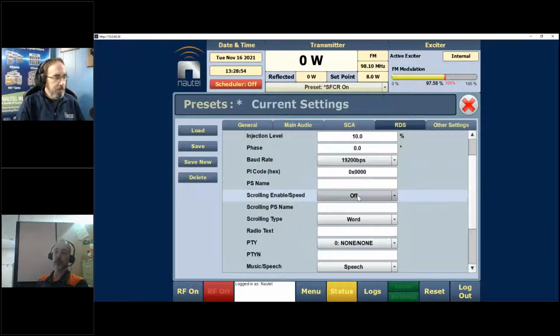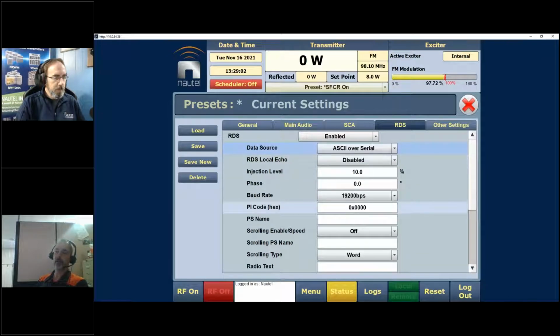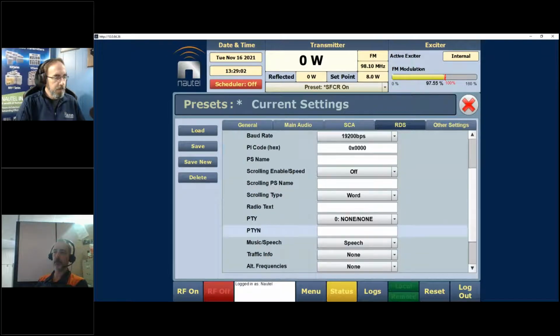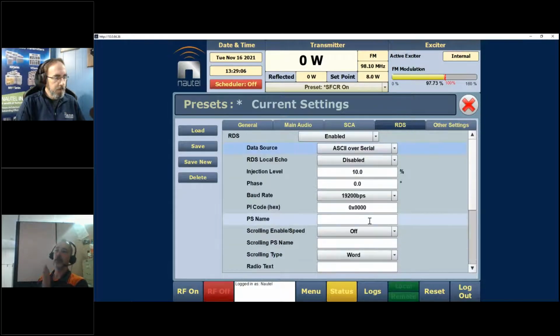And it also allows the audio player, the 5.2.1 software. But this is where you would enable your RDS and set up your static information. If you're feeding in data, and the transmitter doesn't receive the data, it will broadcast the static message that you've selected. If you start getting data, it will update the RDS message being broadcast, not the static field. Right.